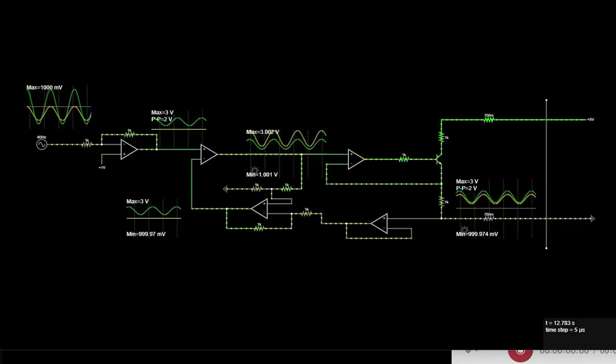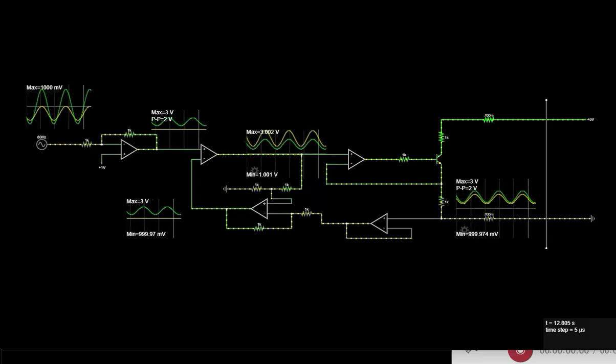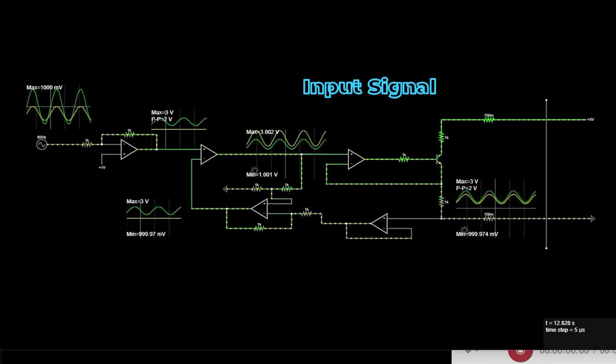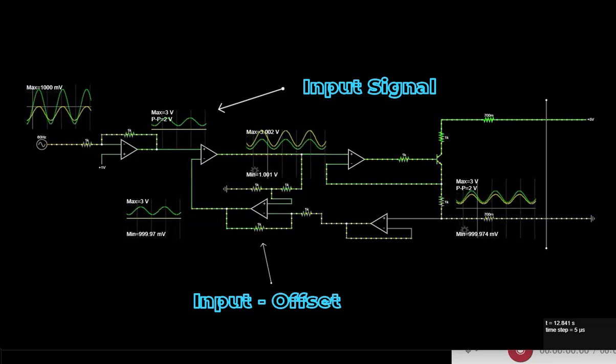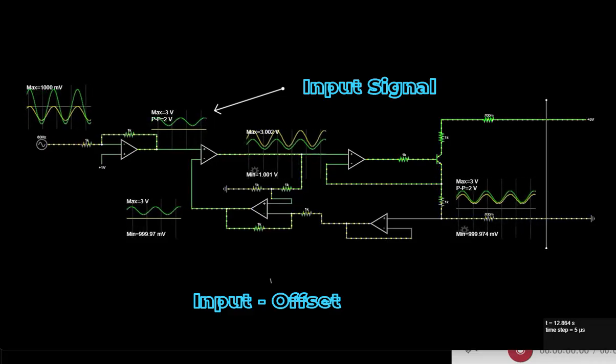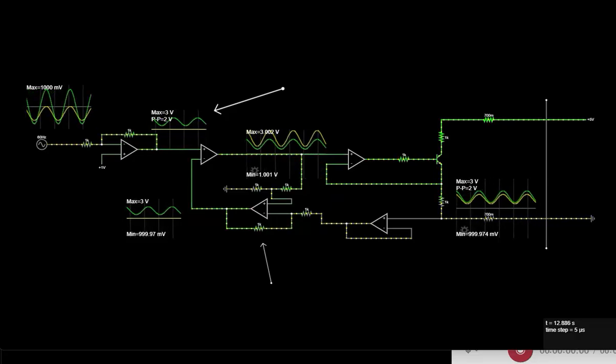To take the difference between our input voltage and offset voltage from the return wire, we use a difference amplifier, which we then feed back into an op-amp, where it compares it to our original signal, and then makes the corresponding adjustment to the output to drive the signal slightly higher so it can make the adjustment for the offset voltage.